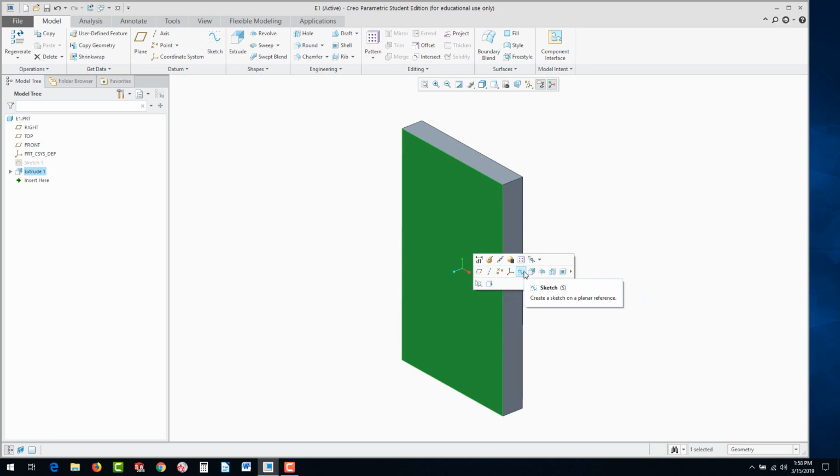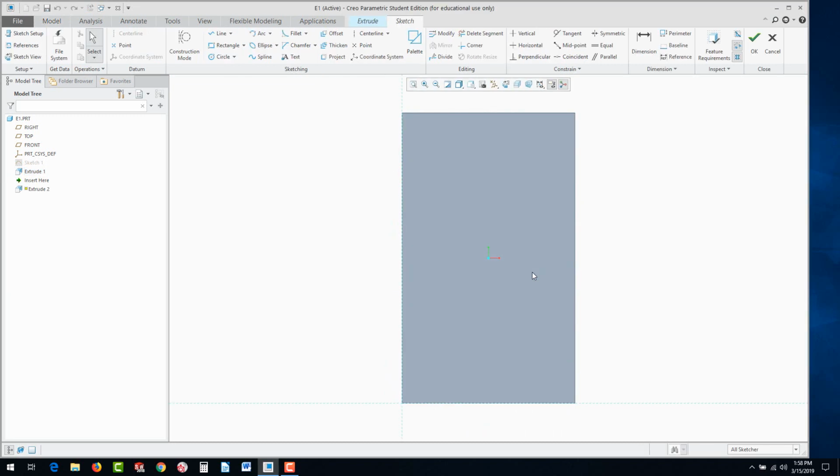things like that. But what we're going to do here, instead of starting a sketch, I'm going to show you another method which actually just goes directly to extrude. And if you know what you're going to do in advance, select the feature. Like if you know you're going to extrude something, go ahead and select it. And I'm going to show you in a second why there's an advantage to pre-selecting the feature before the sketch. Let's go to rectangle again.